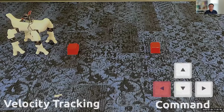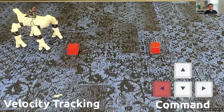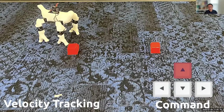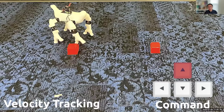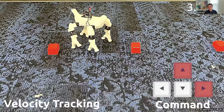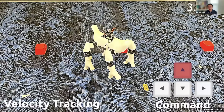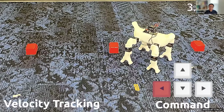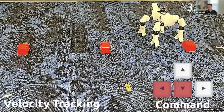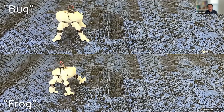Another example we can see here is after the robot is trained, because one of the objectives the human user specified was to track velocities, you can use your keyboard to control the robot, teleoperate it, and move around in the 3D space. Again, all of these were built in less than a day, and the only human input was what you want the robot to look like, and all of the joints were actually figured out by the machine itself. So this is very exciting, especially if you look at the knee joint and the shoulder joint, where the robot can actually leverage these to know how to turn and respond to different velocity tracking commands from different directions.